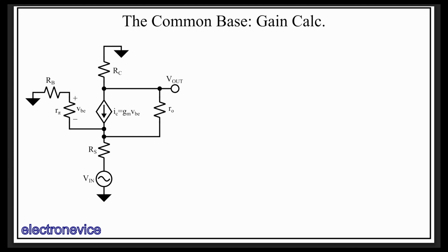It's a bit daunting. I found the best way to deal with circuits that are difficult to solve is to try to find a voltage or current that we can pretend is static and solve based around that. Then substitute in the real expression for that voltage after the fact. So, what would make this circuit easier to solve? Well, if I knew what the emitter voltage VE was, it would be trivial to get VBE. So let's assume we know VE and solve for V out in terms of VE.